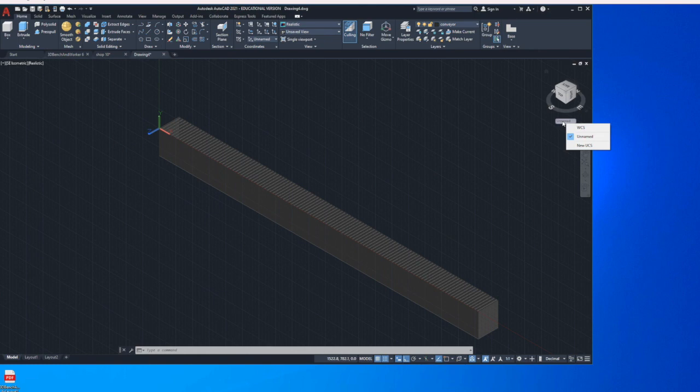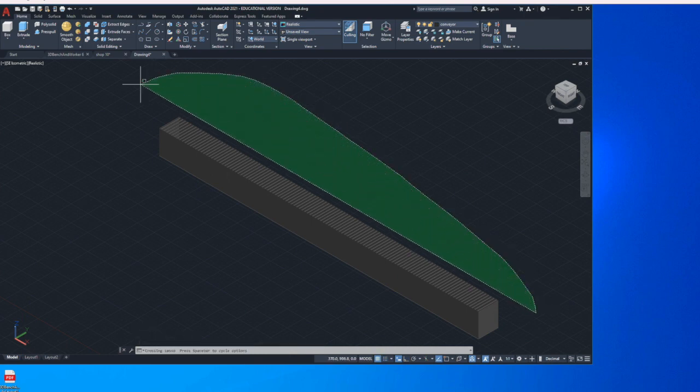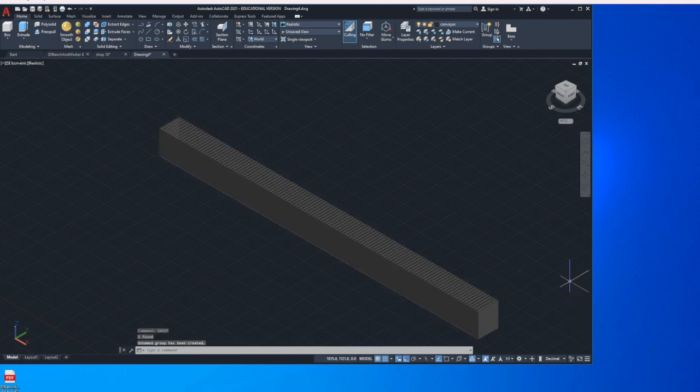in the shop building. So let's go back and go to world coordinate system. And one thing I'm going to do here, because I've got quite a few pieces here between the array and the edges of the bench, so I'm going to just circle everything here, and I'm going to type the command group, which is going to keep everything locked together for me now in a nice tidy bundle. I won't have any risk of pulling things apart when I move.